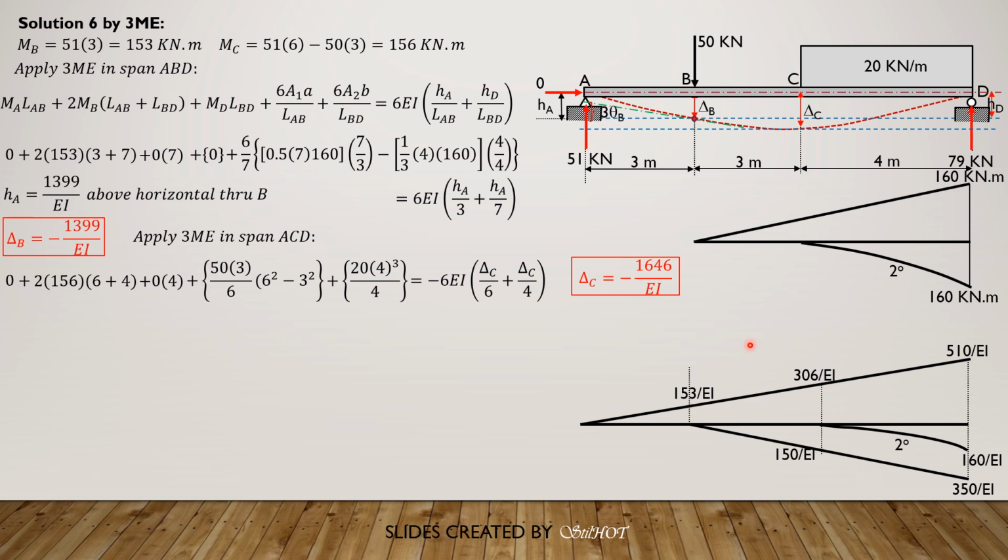So this is 3 theta B, because tangent of theta B equals opposite over 3, so the opposite is 3 theta B. This very small distance here between A and the reference tangent at B is the deviation of A relative to B. So therefore, deviation of A relative to B plus 3 theta B, we just treat them as positive, equals HA supposedly. But we remember that theta B is negative.